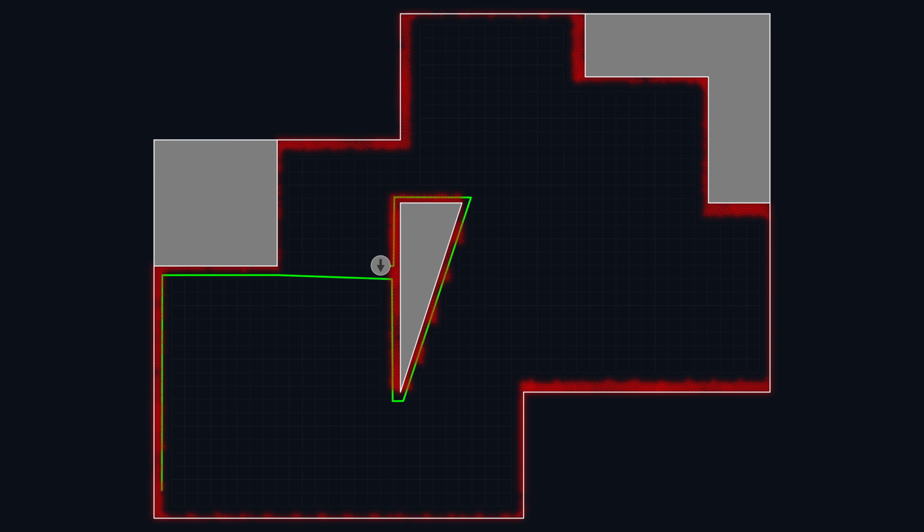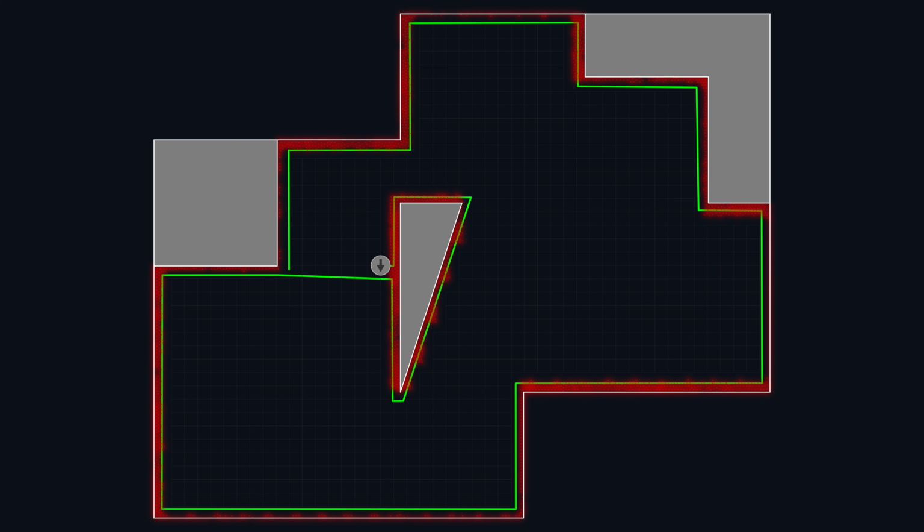If we want to improve the rating given by such a function, we'd certainly focus on increasing the percentage of the room that's cleaned. One option might be to make the grid smaller, which would increase the area the robot covers, but this would also slow down the cleaning process quite significantly, so it wouldn't really improve the rating. A better approach might be to add extra instructions to our existing path, telling the robot to circle around the edges of the room and obstacles. This would allow the robot to clean most of the spots it missed before without slowing down the cleaning too much.